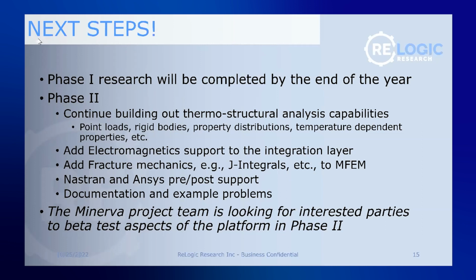And then we're looking to add electromagnetic support to the integration layer, so being able to bring those pre-post processors to setting up electromagnetics models, and then also adding some fracture mechanics enhancements, things like J integrals in MFEM. As I mentioned earlier, we're going to add support for Nastran and ANSYS pre-post processor software, and then build out that documentation and example problems to hopefully get to a beta releasable platform at the end of the project.